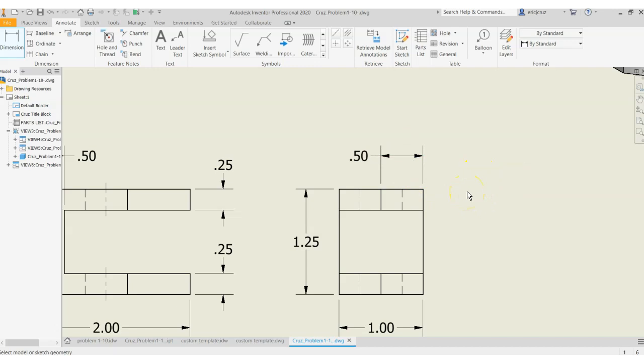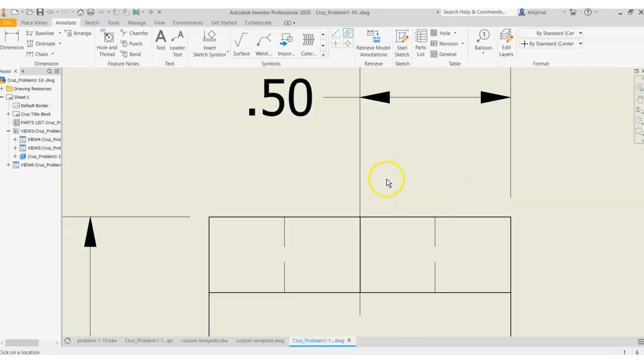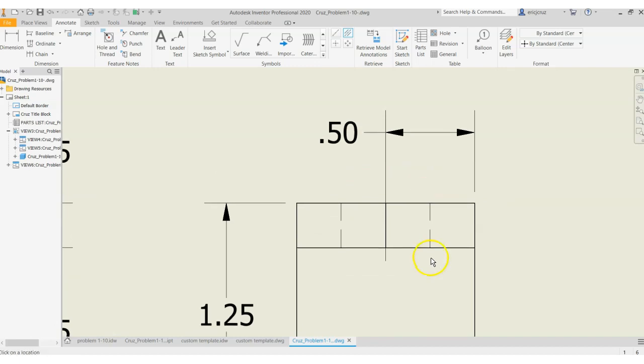We're going to put a center mark here and here, but I'm going to get rid of it. But what? Just watch. Don't do this step yet. But just watch. If I click here and here, I get my center mark. Notice how it clashes with the extension line. That's okay.